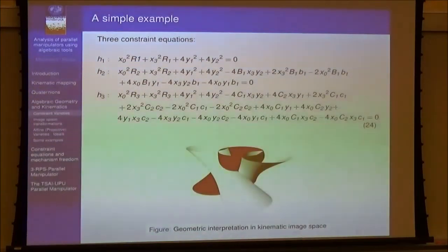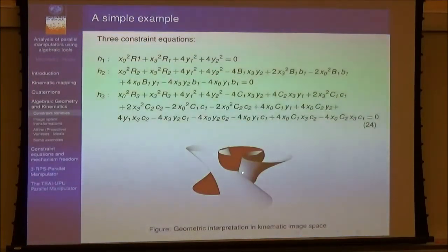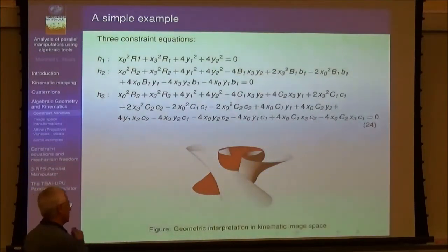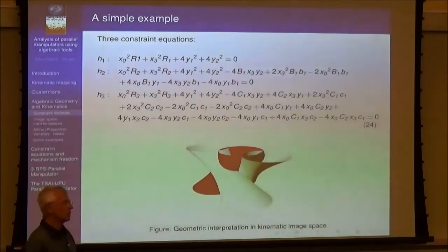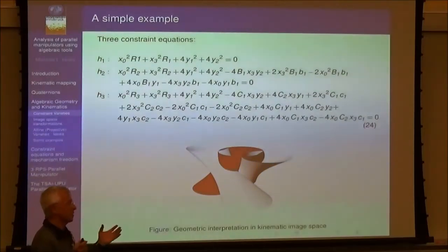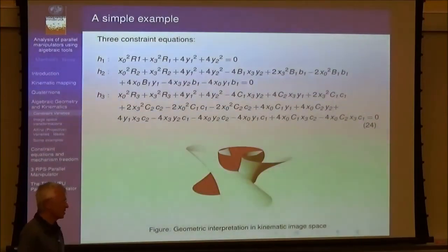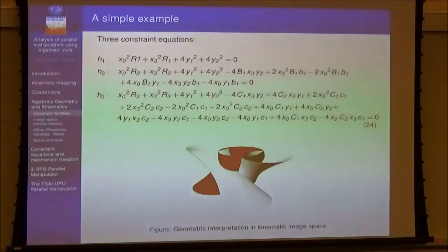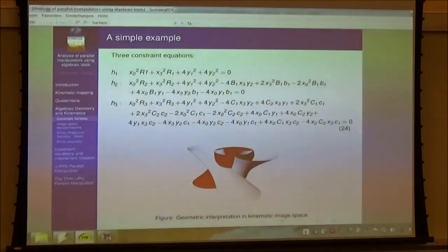These are special hyperboloids, as Jeff said in the morning. They are circular hyperboloids. And all we are interested in are the common points of these 3 hyperboloids. And this can be done. Once you have set up this system, you can solve the direct kinematics of this planar Stewart-Gough platform without specifying the Denavit-Hartenberg parameters, the design parameters of this system. And I can do it so fast that I can show it immediately to you in a worksheet. Let's do it.